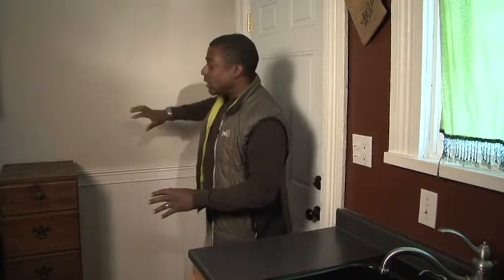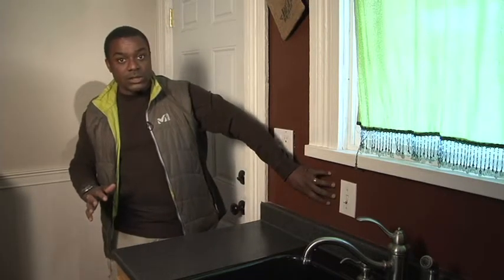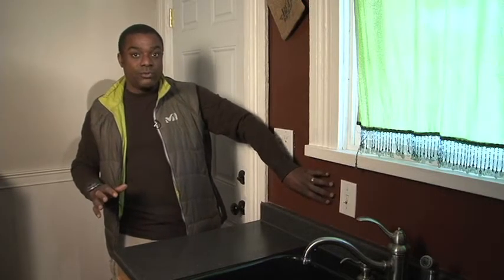When we were outside, we noticed a change in our roof pitch. When we got inside, we discovered that the kitchen is an addition from the main structure. So we want to make sure that we check our wall construction and insulation levels. On our south wall here, we still have masonry construction. But on the west wall, we have drywall that appears to be furred out from our masonry construction. So we want to do a little more investigation here to see if we can add insulation to this wall and improve its R value.